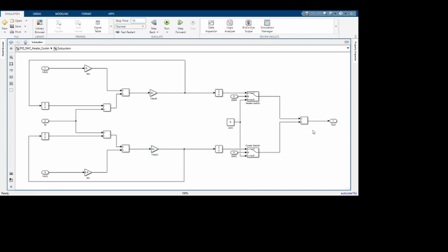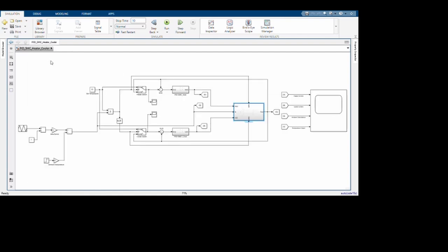I've gotten two switches here again, which either turn on the heating equation or the cooling equation, and eventually the temperature is added. Now you might be wondering, it does not make sense to add the temperature, right? It actually does. The reason is because when the heater switch is on, the cooler switch is going to be off. That means this output is going to be 0. So no matter what happens, if you add 0 to this temperature, it's still going to give you an output temperature. And this is how most HVAC systems work. Heating, ventilation and cooling systems simply have their controller architecture have one switch turned on and one switch turned off, and add both of the outputs. That really helps with the simplicity of the architecture, and also this is a very reliable method of applying it.